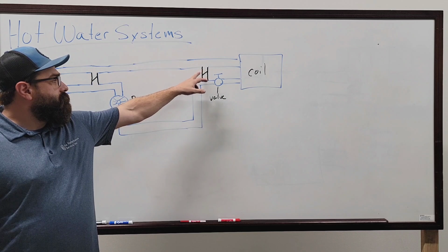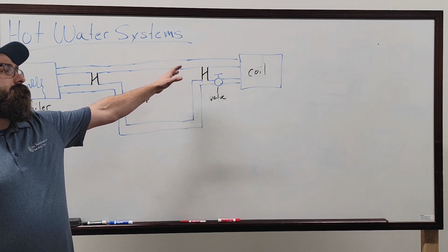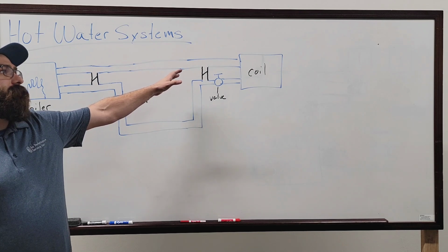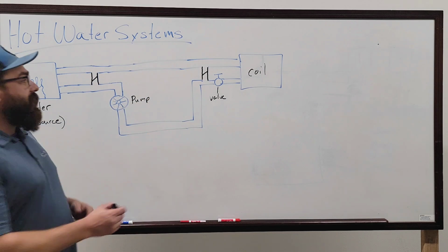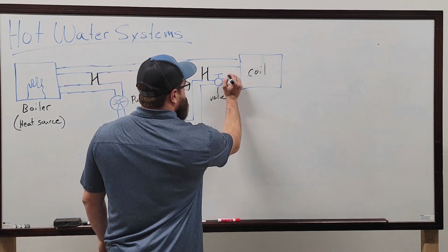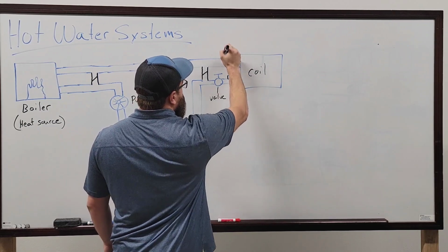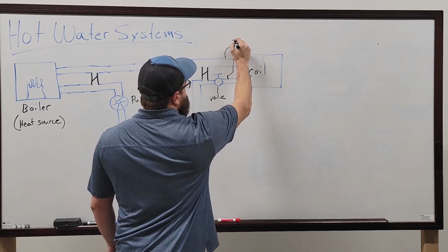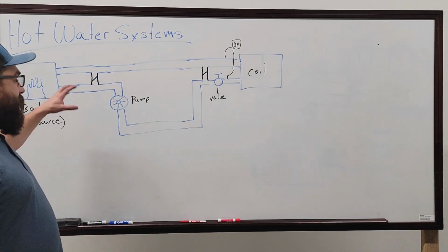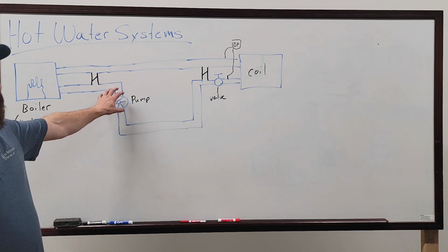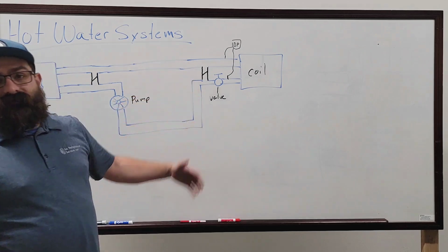This is, I guess, the same thing too, but it's focused on pressure versus GPM. So what you would have here is a pickup and a pickup that then come to a sensor. This sensor would monitor the differential pressure of the loop, feed that back into a controller, which then modulates the pump or this valve to maintain differential pressure.